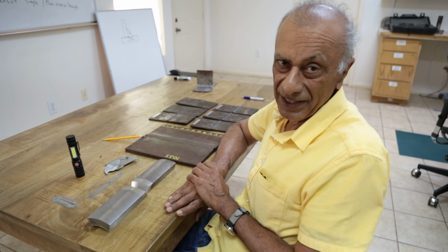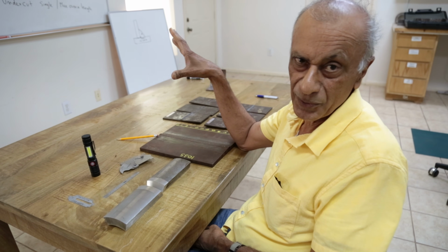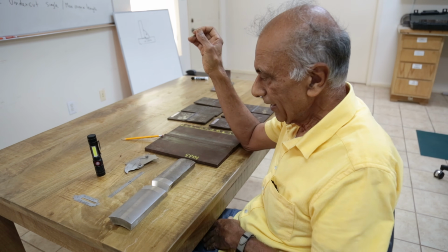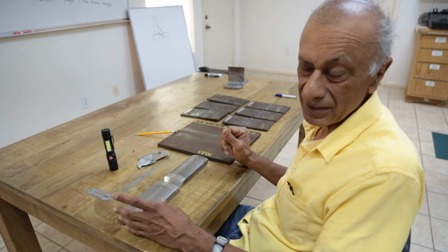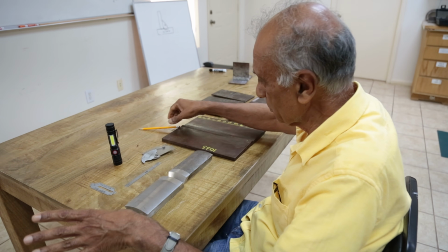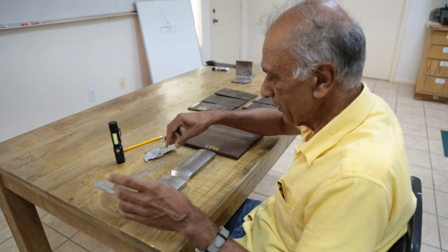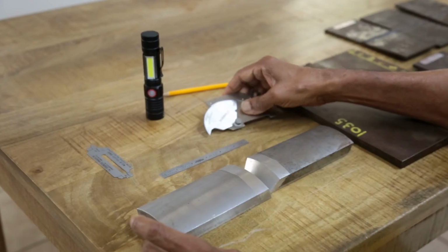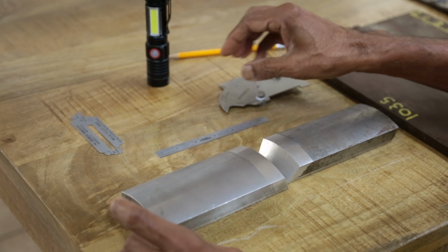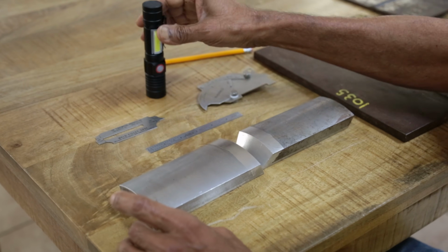Okay, I just gave you the steps on doing the visual inspection. Now we will go through an actual demonstration. First thing, you need a data sheet to document all your results. And then these are the basic tools. So really you don't need many items as tools. You just need a ruler and this cam gauge. It does a lot. And then you will need a fillet gauge if you're doing fillet welds, and a flashlight and your pencil or pen.